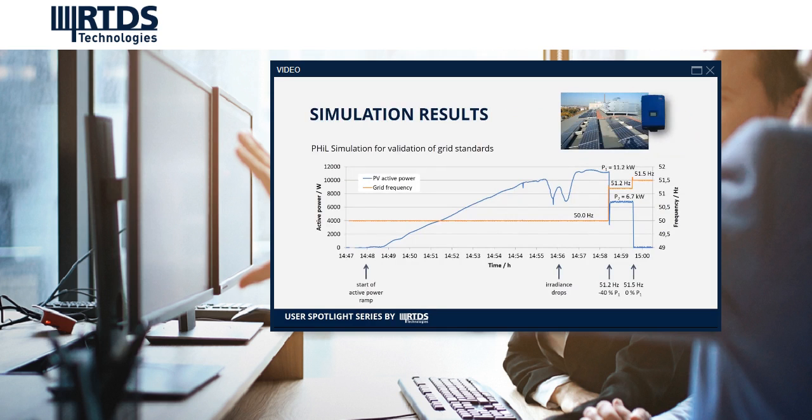The application is a validation of the PV converter to fulfill grid standards, which I did in the measurement you can see on this slide by adjusting the grid frequency. At overfrequency, the converter shall reduce power, and finally at 51.5 Hz shall shut down.